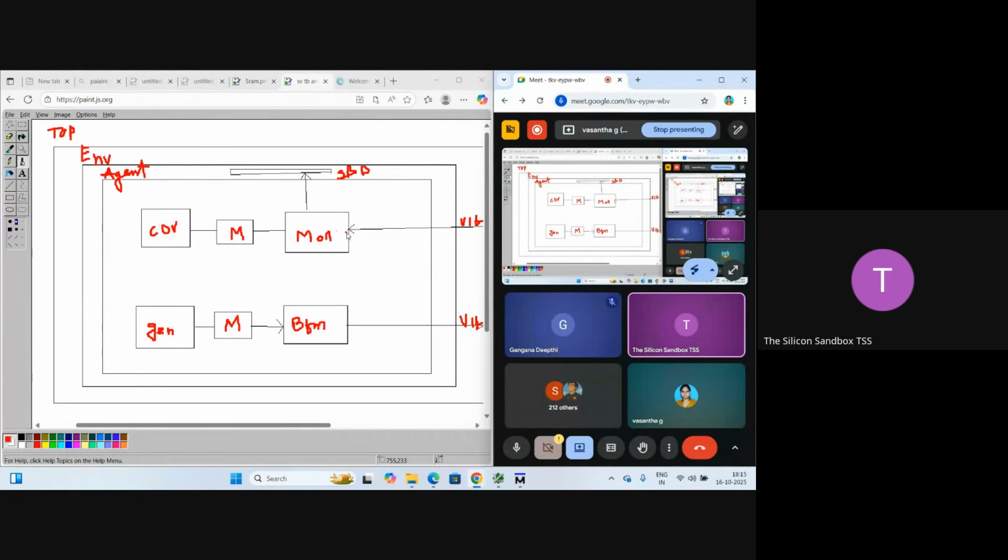Yes, ma'am. Okay, so we already discussed the Verilog state variables, right? Verilog supports 4-state variables. Why do we require the 4-state variables? What are they, that we have learned in the introduction of Verilog? Logic 0, logic 1, unknown and high impedance, right? All these variables are only for simulation purposes, not for design purposes. Because there are 4-state variables, simulation takes more time.